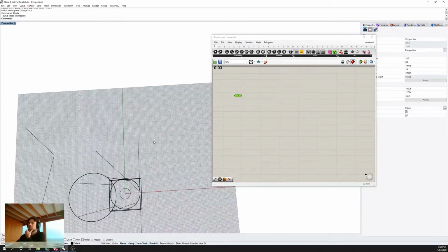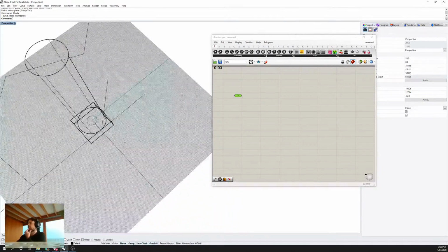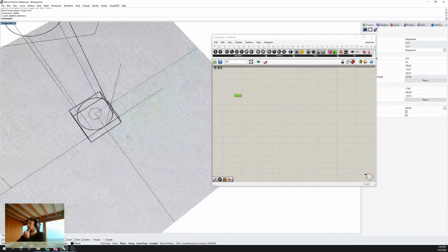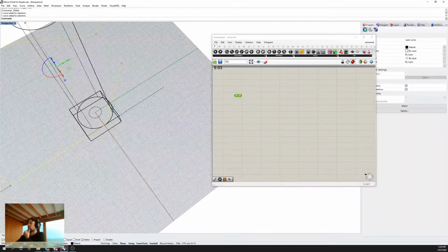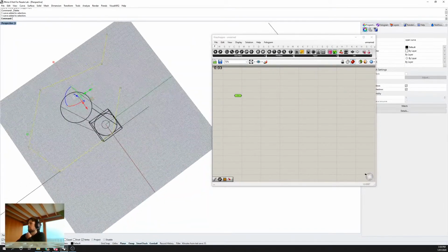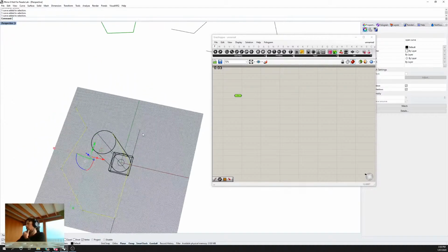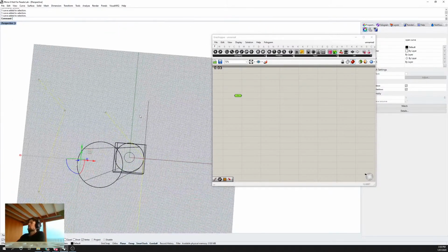So for every single bend in the part, these are essentially the steps that we need to parametrically go through and produce. And there's a little bit more complexity here as well because our bender is going to introduce a fillet into this part as we bend it around this bending radius, the bending block. So we would want to take that into account as well. But that essentially would give us enough information to go by.